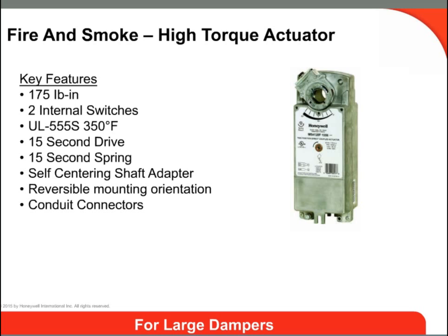High torque models have 175 inch-pounds. Just like the lower torque models, they are available with or without internal auxiliary switches. They're designed to pass UL 555S requirements of 350 degrees for 30 minutes. They drive open and spring close in 15 seconds.